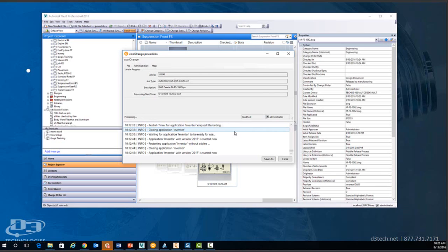So it's creating the DWFs of all my IPNs and that's set in my life cycle, right? I can set transition states in every life cycle to create a DWF file that's needed, update the revision block as you're seeing now, do all those kind of things in the background, synchronize properties so that all the DWFs and everything are current. And it's going to update the revision block. And we want to do all that stuff before we create the PDF file, right? We want PDF to be last. So we set those priorities on our job, and here's the PDF being created.